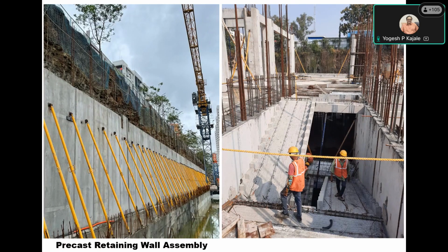These hollow core or solid walls all depend on how much continuity is required. Instead of having a full hollow core, we can have two hollow cores at the end boundary locations, and the middle part could be a solid wall.